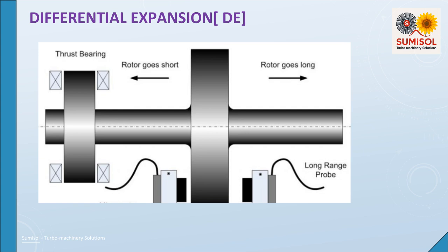Therefore, during transient phases of operation, startup or cool down, heat-soaking dwells are used to ensure that thermal expansion or contraction does not cause rotor-to-stator contact. It is common to use non-contact probes, eddy current probes, attached to the turbine casing to observe the rotor, thereby measuring the difference between the movement of the rotor and the casing as they thermally expand, to measure the differential expansion. Ideally, the two probes are mounted onto the same dual probe carriage as shown above, but other arrangements can be accommodated in the system configuration, but are more complex to set up.